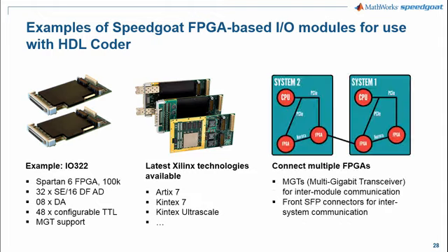In order to further scale up this solution, it will soon be possible to interconnect multiple FPGA cards within one or multiple systems via multi-gigabit transceivers. We leverage the fast serial Aurora protocol for this purpose. All new Speedgoat FPGA cards by default have onboard MGT support, and the performance and mobile target machines have default integration of the necessary physical connections.